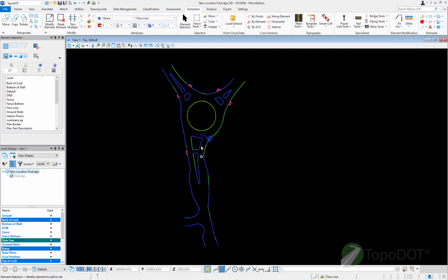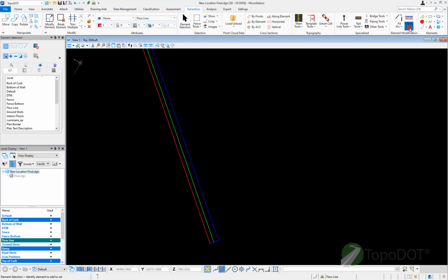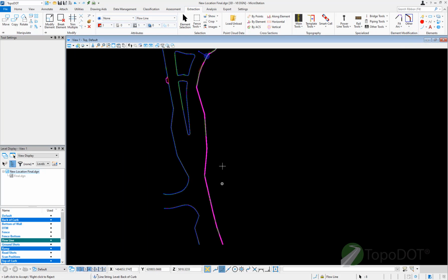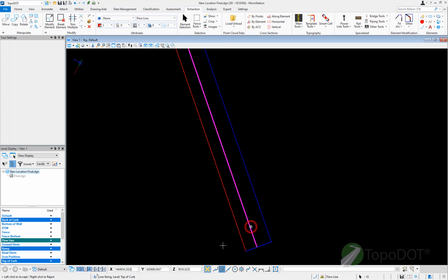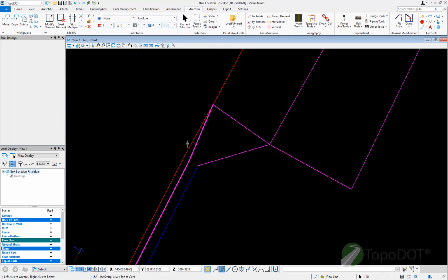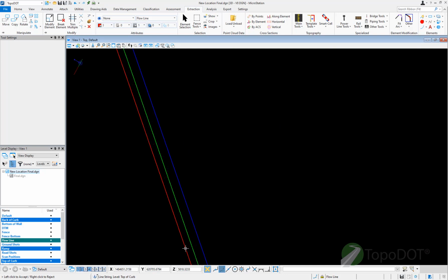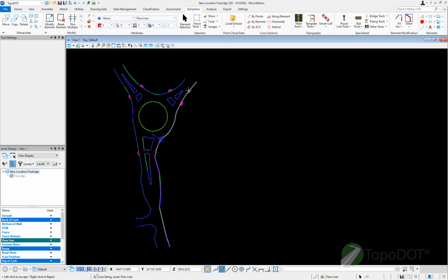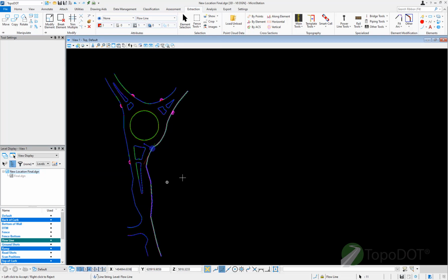First of all, these breaks have been created in segments. So before I run the tool, I want to make sure that these lines are joined together. So I'm going to use this create continuous element to join these segments together for as long as it can. And this is also going to help me ensure that these lines are touching at the ends, that they're continuous. And if they're not, then that means I need to adjust an elevation or a position of the end of that node to ensure that the lines are touching.